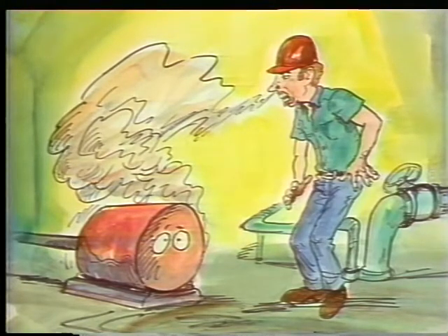That includes common sense. Say you smell burnt insulation and the motor's a squirrel-cage motor. Well, the rotor in a squirrel-cage motor doesn't have any insulation, so the problem's got to be in the stator. But suppose you smell burnt insulation in a wound rotor motor. There's insulation in the stator and the rotor in that kind of motor, so where do you look first? Well, if you look in the windings of the rotor, you might be able to see the burnt insulation. If you do see burnt insulation, you're going to have to test the rotor.